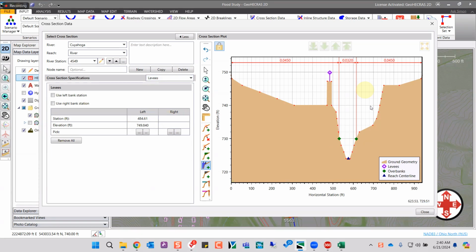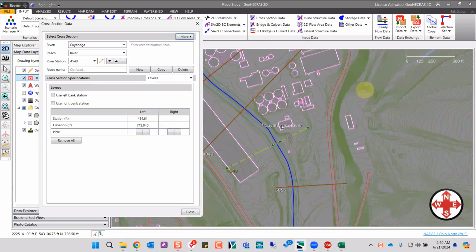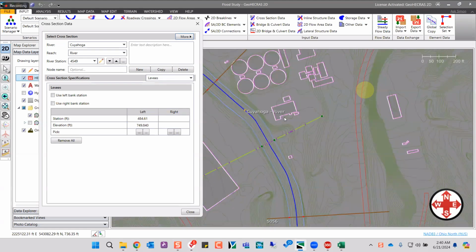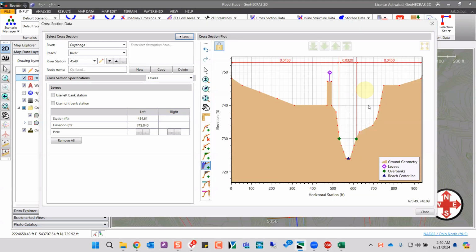Now, on the right overbank area here, let's take a look. Here you can see it's kind of a dead swale. There won't be much active flow in this region, and you might have water somewhat stagnant in this portion of the river. Now, this scenario would be perfect for you to define your ineffective flow areas. Same happens around your bridge openings as well. You can see bridge openings are comparatively narrow when compared with your river reaches.